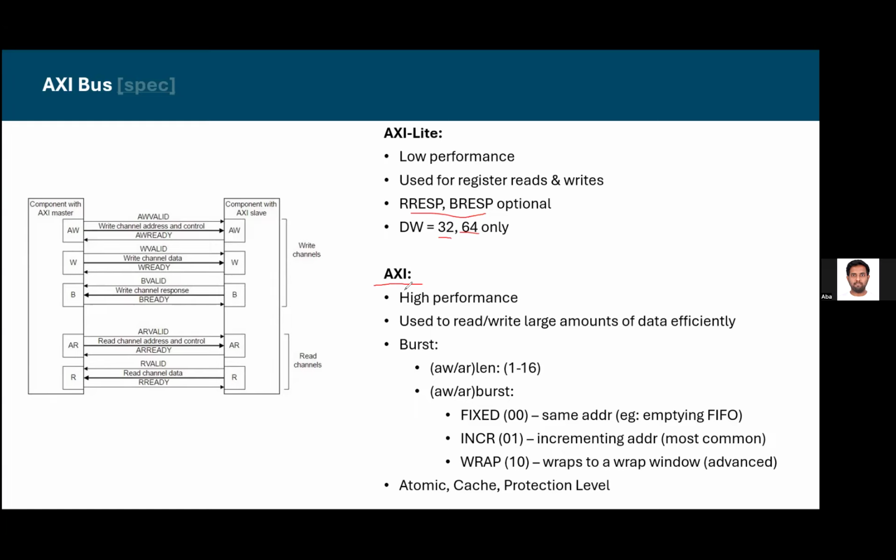Why? Because now your bus will have a lot of activity, and if you are sharing this bus with a lot of other IPs, then other IPs can't use the bus, and you have a bunch of problems. And you don't want to be doing this counting anyway. So to solve this, you have the burst. This is the key feature of full AXI, the burst.